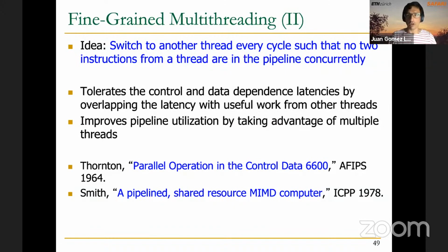And a typical example of long latency operations are memory accesses, right? Because when you go to the off-chip memory, even if it's HBM2, which provides very high bandwidth, the latency, the number of cycles that you need for the access, is still very long. Recall the example of memory banking, I was talking about the latency of 11 cycles. Usually it's longer than that. Usually accessing the off-chip DRAM in current GPUs takes several hundred cycles, right?